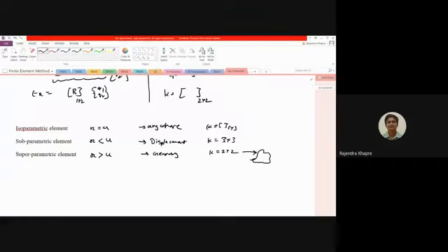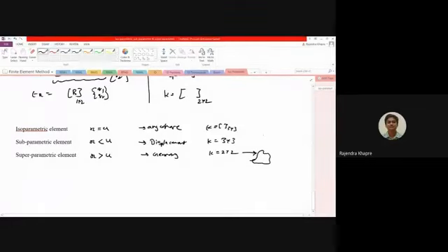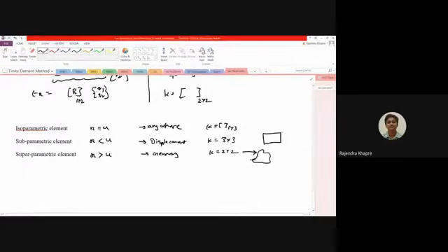For example, your geometry is very simple. Let us say you have a simple rectangular object. Here the geometry is very simple, but you want a detailed variation of the results. In that case, for simple geometry you can use the sub parametric element, but your deformation will have greater importance and your stiffness matrix will be of a very large order.